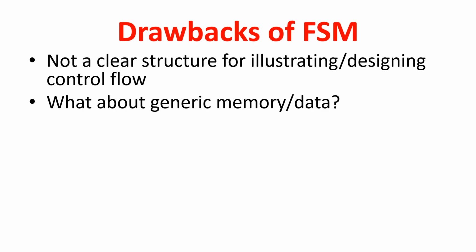That means we will not be able to model a register using FSM. A 32-bit register or 32-bit counter, we will not be able to model. Then what is the use of FSM? This is the major drawback. FSM has the problem of state space explosion. Whenever the data components or memory components use larger bits, it is very difficult to model using FSM.